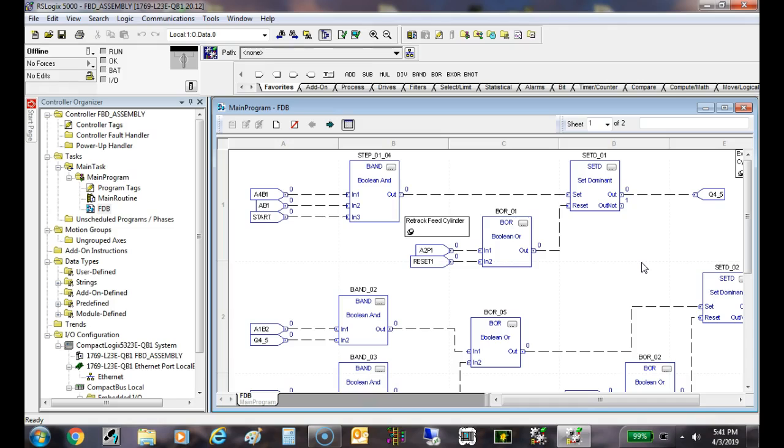So Boolean AND, so it says for this output right here to go true, this sensor right here has to be true, this sensor has to be true, and the start button has to be pressed. It's correct. Then it would fall into there, right? Now this is what we call a set reset latch. So that would set it, that would cause this output to be true.